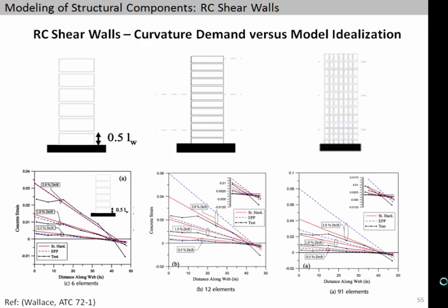And I think Graham Powell, who has worked a lot on modeling walls, really will advocate, for the gauge length, if you will, or for the size of these elements, to pick them as a story height or half of the wall or pier dimension, and not to go finer than that to avoid these sorts of problems.